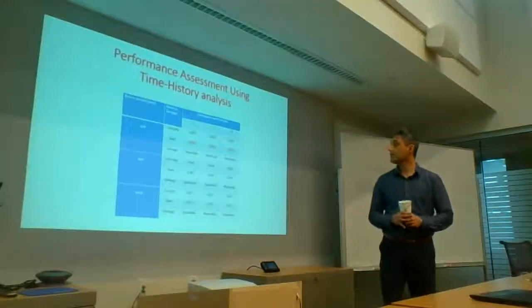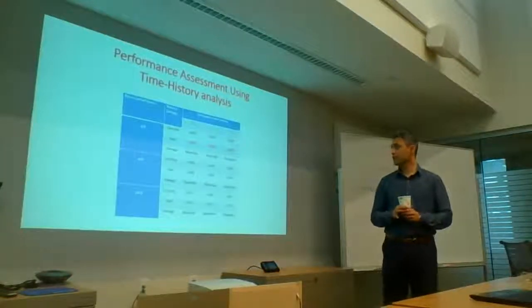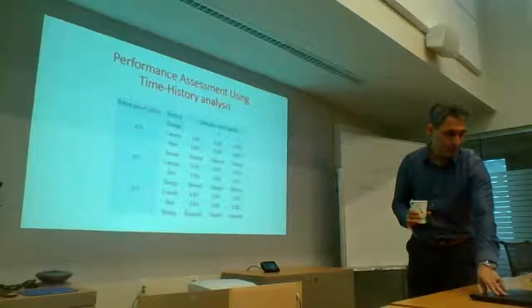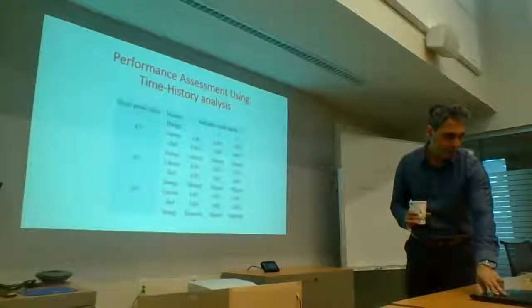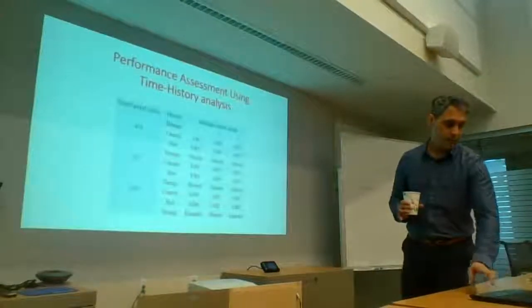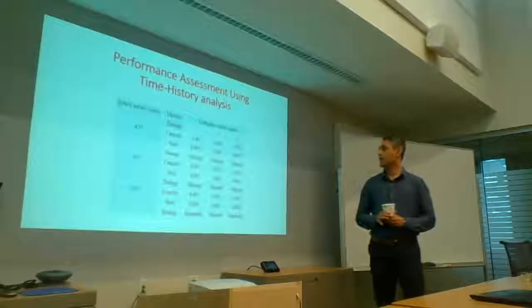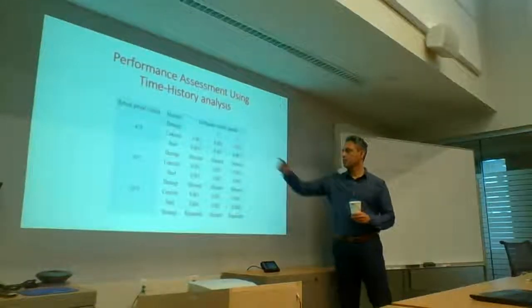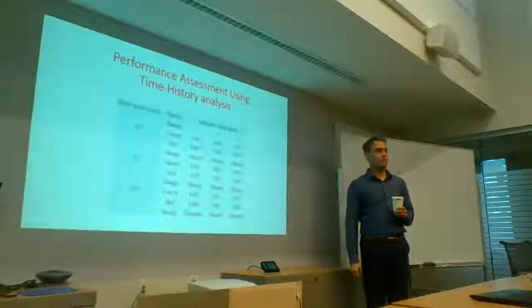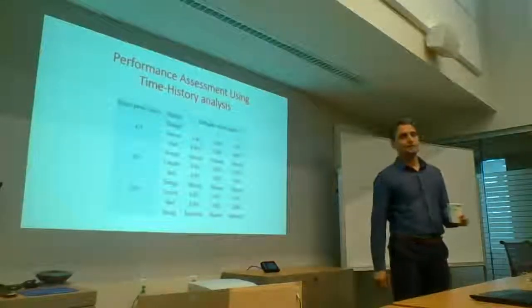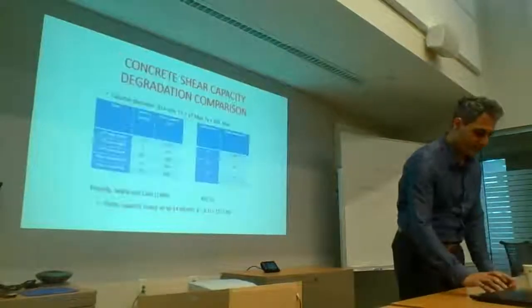Even with a lot of reinforcement in there, we weren't getting what we needed until we got to about 5.7% rebar, and then we barely met this minimal damage criterion for 475. But 6% rebar is not to be put into a system.